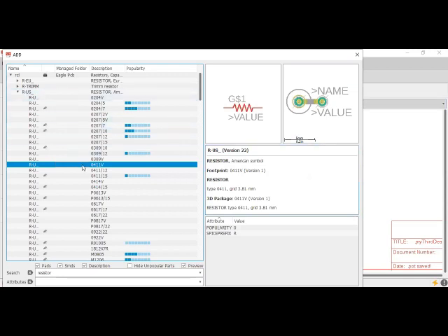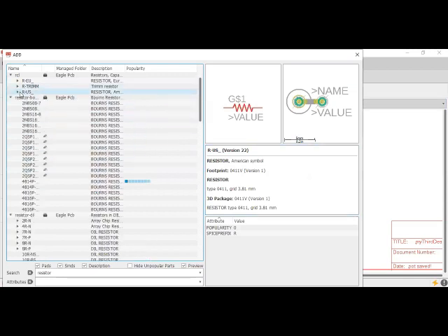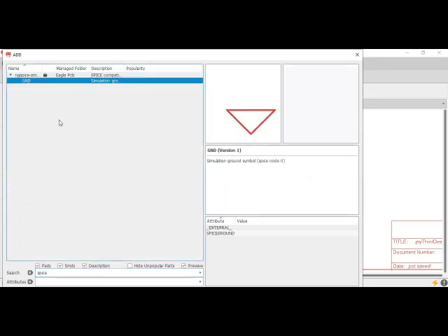So we need something very important as well, which is a voltage source. Normally we are supposed to make use of the ngSpice voltage, but it's not showing here. I think it does show in my other Eagle, while I'm using Eagle 9.6 here. The ngSpice library, which is for simulations, has a lot of components as well.